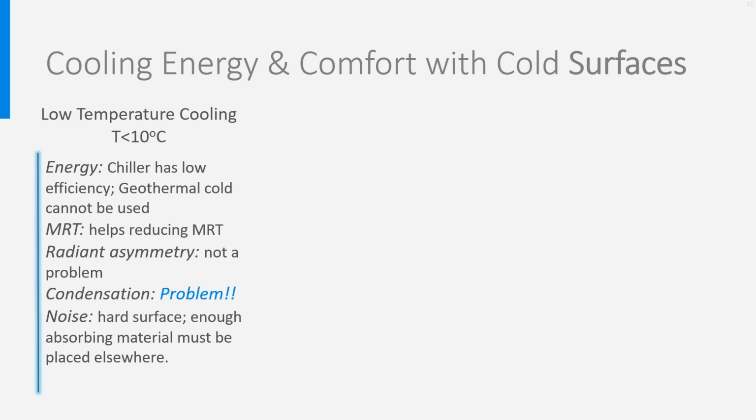Geothermal cold cannot be used either. Condensation on the panels may be the biggest problem. Air at 24 degrees and 41% relative humidity condensates at 10 degrees. So, unless the room air is very dry, the cooling plate will become wet. It will rain inside. That's why such low temperature systems are not recommended. Additionally, the panels are hard, so not very favorable to the acoustic.